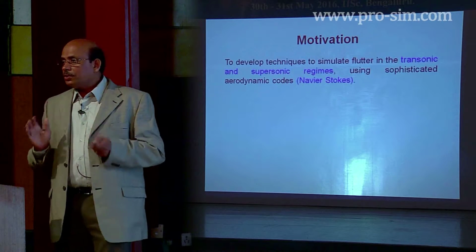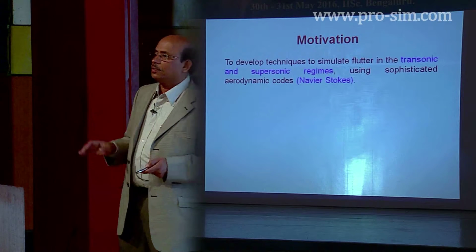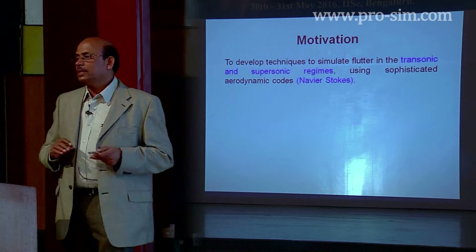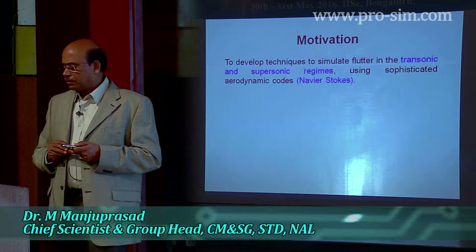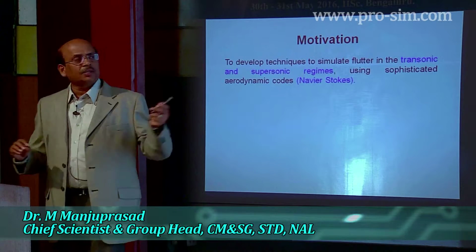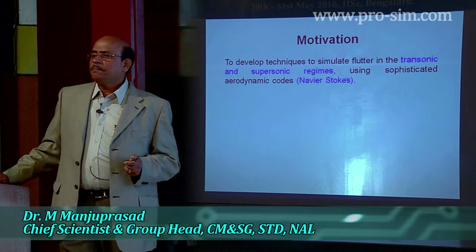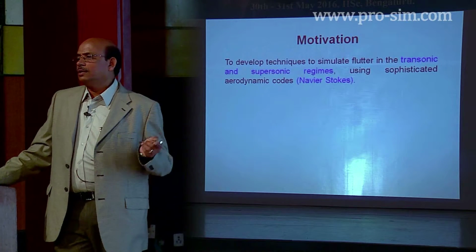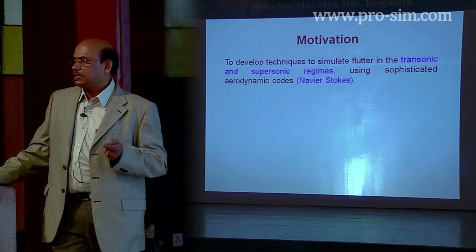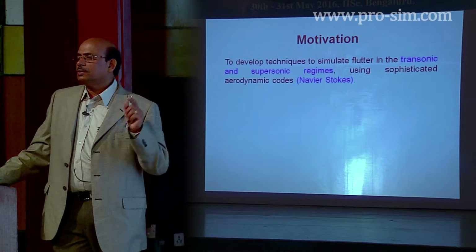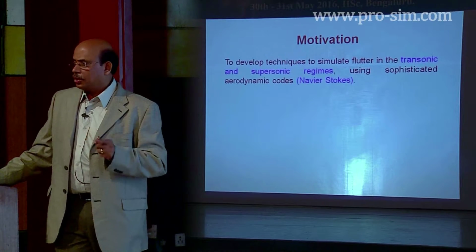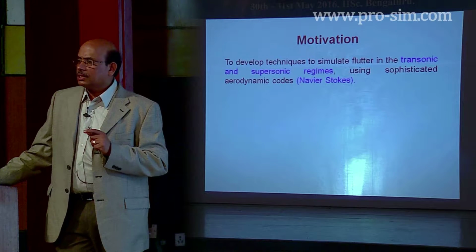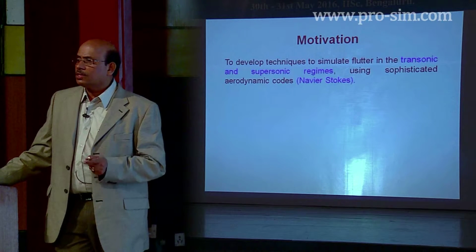A lot of groundwork was made in our division for developing methods around this. The basic interest and motivation for developing these methods was that most of the classical methods, which are also available in various software tools like Nastran, solve the flutter problem in the modal domain, and they are effective in solving the aeroelastic problems in the subsonic and the supersonic regime.